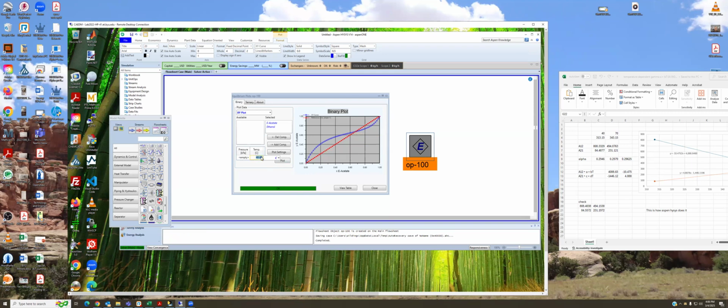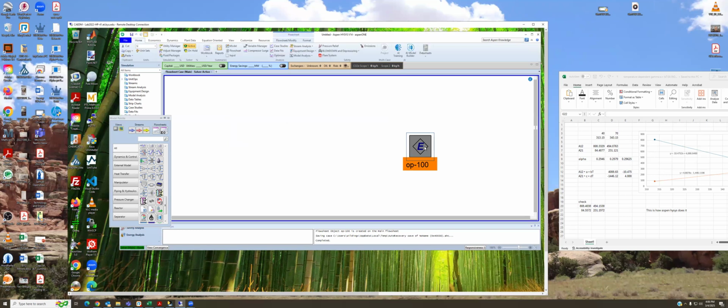We can also look at the 70-degree set and see that the azeotropic composition has shifted to about 0.55. So that's comforting, and it also confirms to us that we have accurately input the parameters. So now let's close this, and we'll take off this equilibrium operator and get to our simulation.